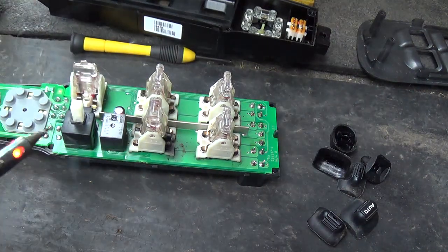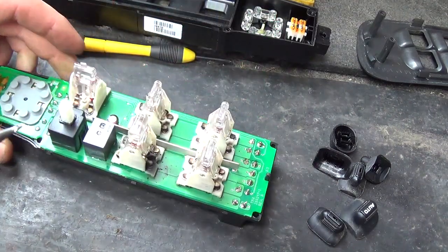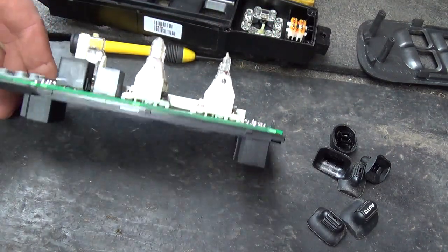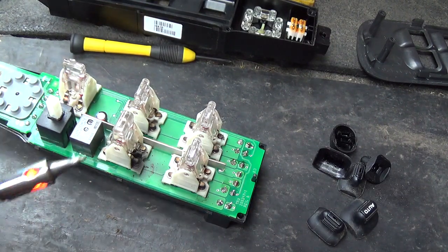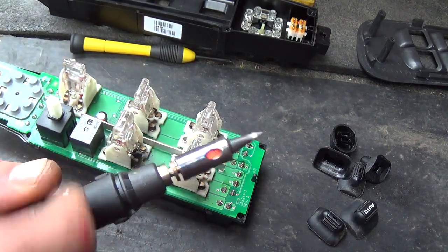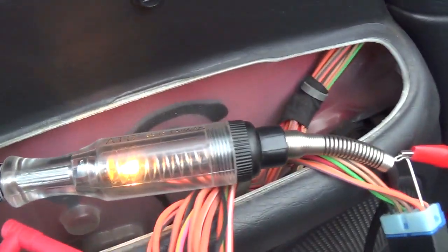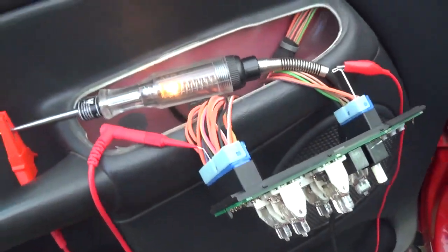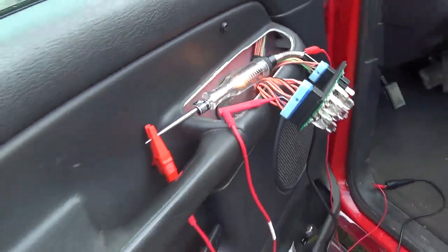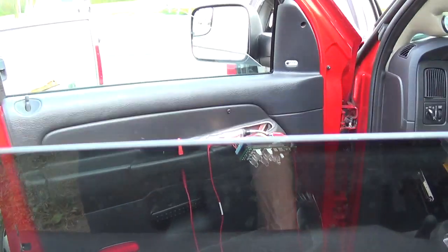Keep in mind I had a lot of arcing and stuff, so the carbon builds up a little bit. But I think right now we should be good in shape. Put this back together. We can actually plug it in right now and see if the windows work. Alright, so we're on that pin again, the one that was intermittent. Now we got constant power on there. We want to go around to all the switches and make sure that light stays lit and our windows work. So here's the rear. Sweet.